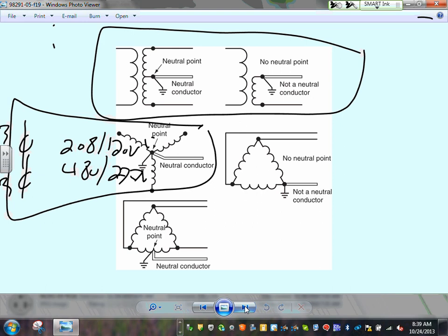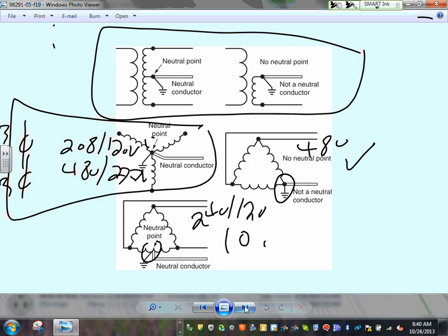That's probably 90% of your systems. These 2 systems, guys, are rarely used. This one is probably used 10% of the time. We'll talk about them in the commercial project. Any comments, guys, about the systems? Derek, when they talk about the power system, it always starts with a transformer. That's you coming from the utility. That decides what type of system you have. Is it 208/120? For example, this one is 480, corner grounded. This one is center tap. This is typically a 240/120 3-phase system.